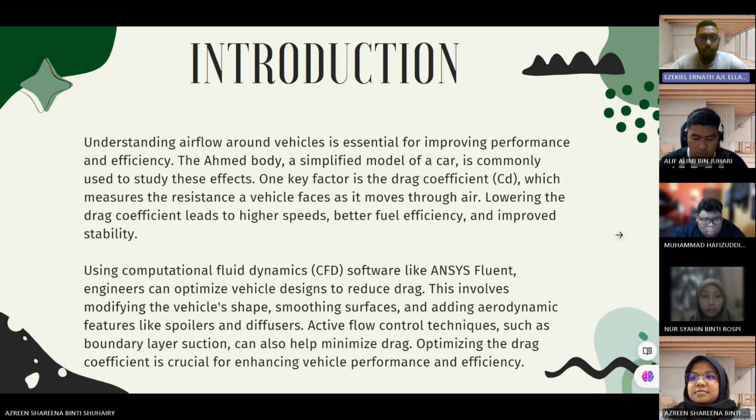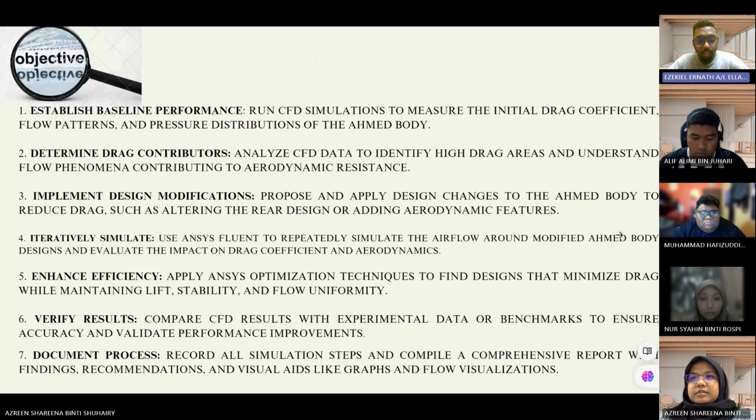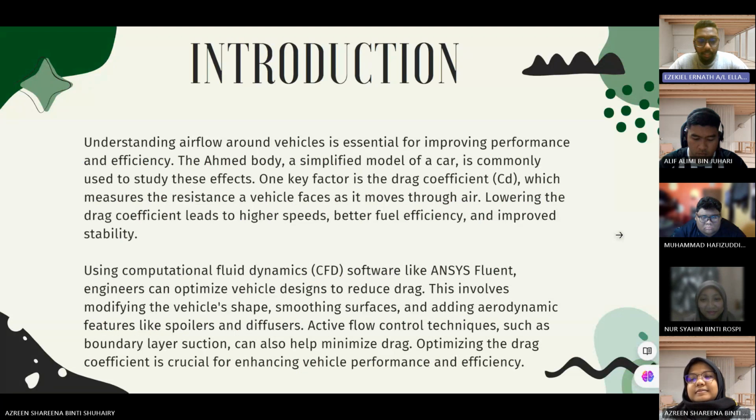Using computational fluid dynamics (CFD) software like ANSYS Fluent, engineers can optimize vehicle design to reduce drag. This involves modifying the vehicle's shape, smoothing surfaces, and adding aerodynamic features like spoilers and diffusers. Active flow control techniques such as boundary layer suction also help minimize drag. Optimizing the drag coefficient is crucial for enhancing vehicle performance and efficiency.